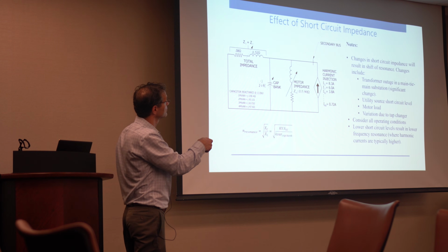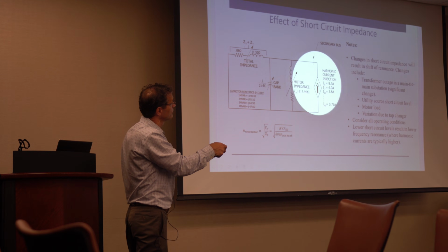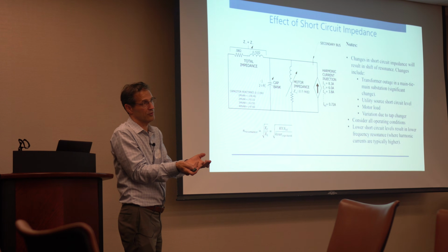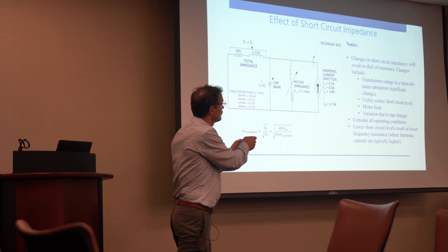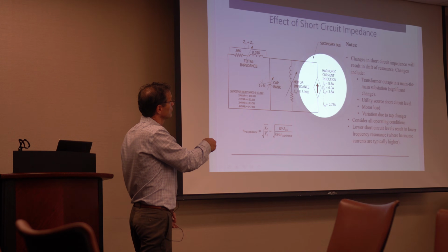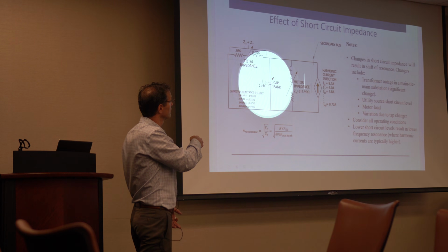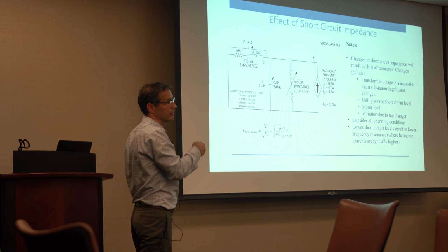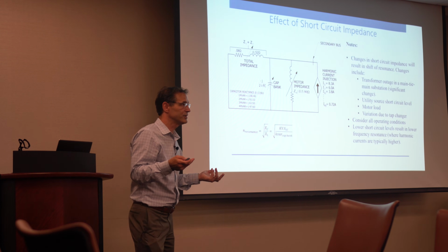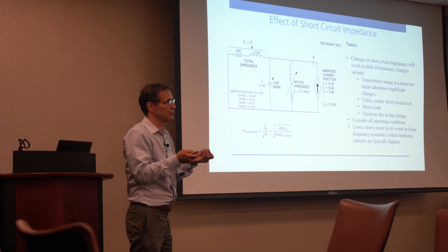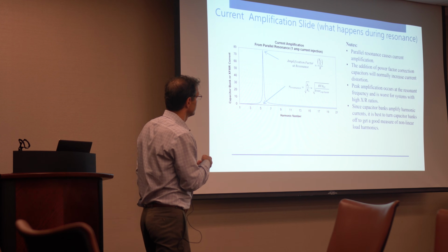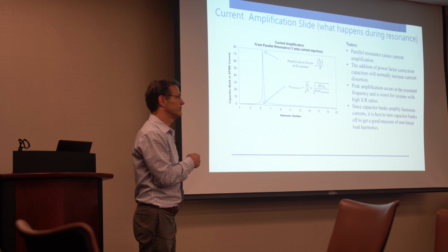If you want to take measurements to quantify this value to put into your model, say you have an existing system and you're trying to create an impedance harmonic model and need a value of current, then if you send a measurement person out, he has to take the capacitor bank off. If you don't take it off, the measurements here are a waste. You can't use them in your harmonic analysis. All you can say is, yes, I have some amplification, but the value of current becomes less meaningful. Something to note: you have to shut capacitor banks off during measurements if you're going on the main.